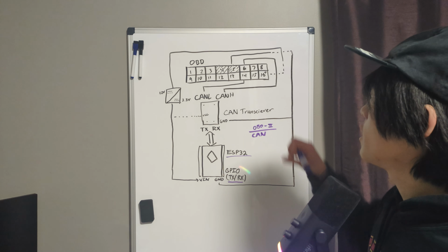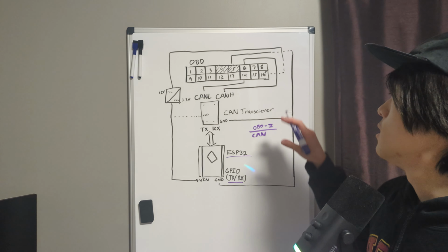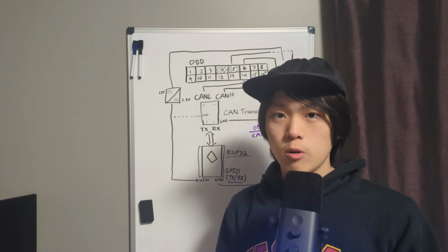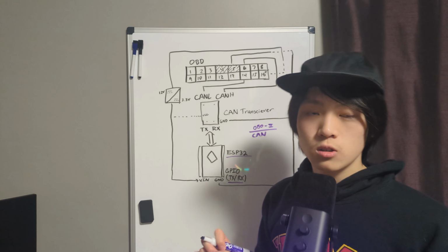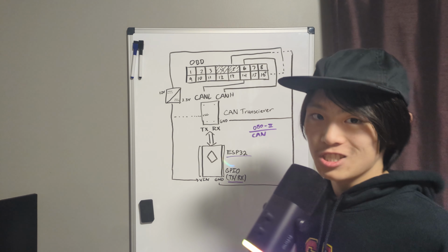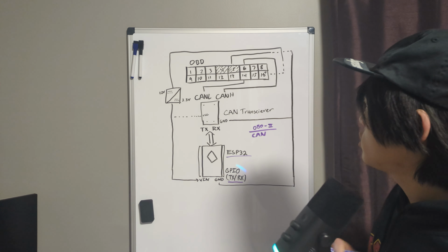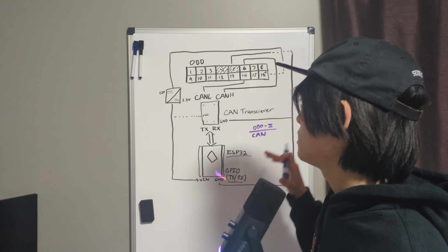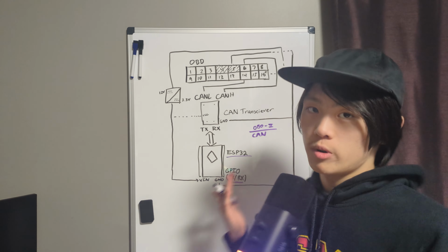And so on your OBD port, on pin 14 and pin 6, these operate what we call the CAN L, or CAN low, and CAN H, or CAN high, bus, which is basically used to transfer the data from our automotive vehicles into a readable form, right?